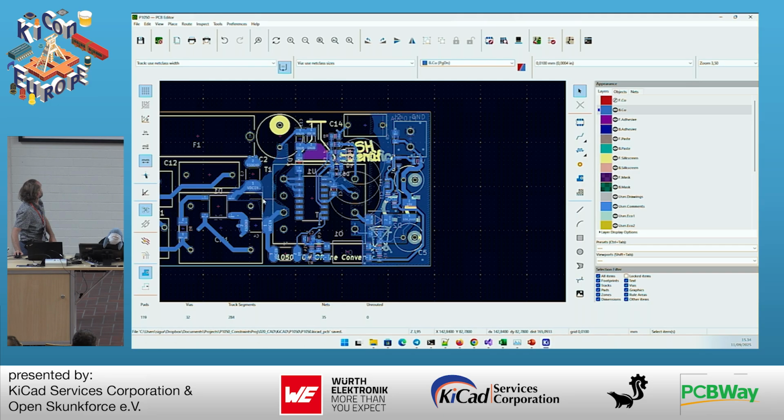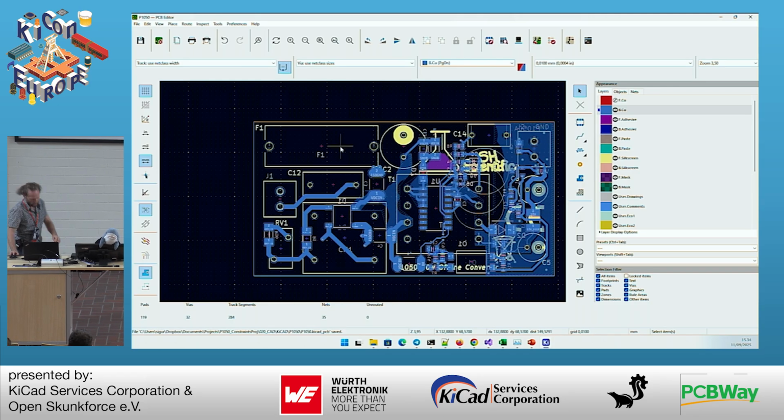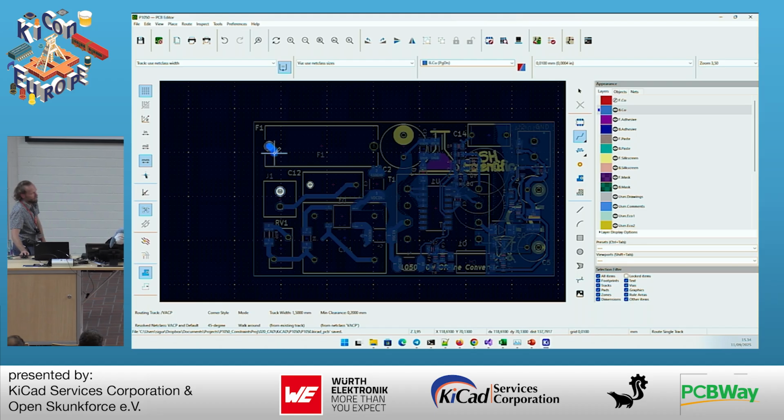And this is a little tricky. Let's say we have a net up here. If you can remember the schematic, this is the fuse. And I remember that this net over here is a member of the same net class. So you can see I can actually drag very close to that net. But if I try to do the same down here, you can see it will keep a clearance that is different from the net down here. So now this particular net has at least 2 millimeters, as you can see here. It has more, but I'm not going to get any closer to the other nets out here.